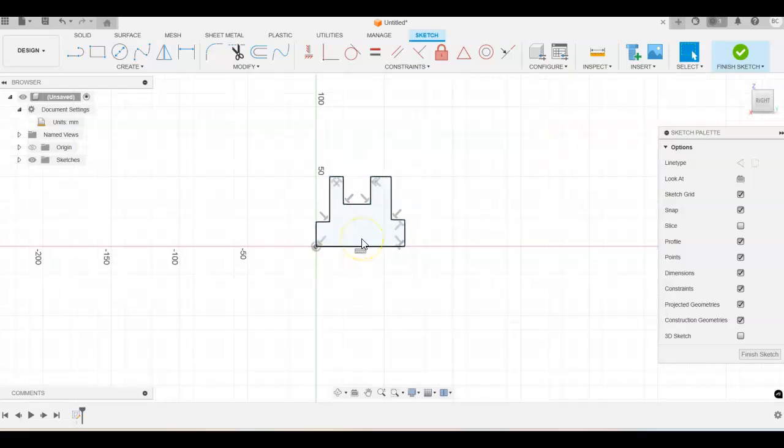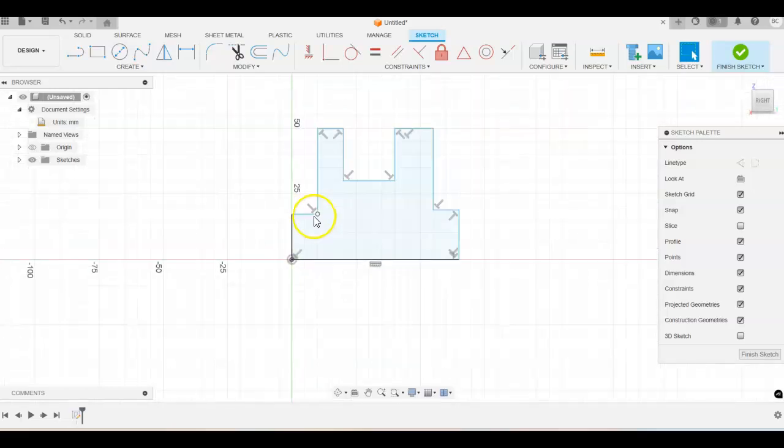So now, a couple of things that I notice. This line and this line share the same dimension, and so do these. Now as you go through, if you are paying attention to those constraints, we can have a collinear constraint already put on here, but right now I notice that I'm definitely not collinear with these.